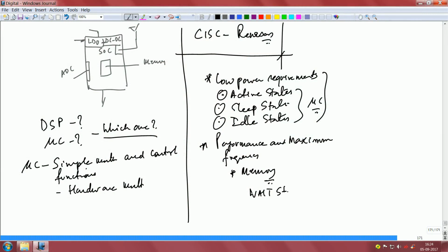See, one thing is clear, memory can pull down your performance drastically. Why? Because if you have a slow memory which is embedded inside the controller and the processor is executing at very high speed, you have to introduce for slow memories what are known as wait states. You are stuck now. There are two types of flash memories in the flash memory technology. Okay.